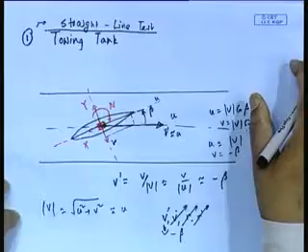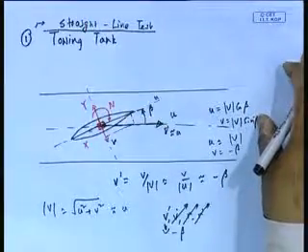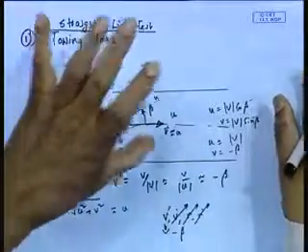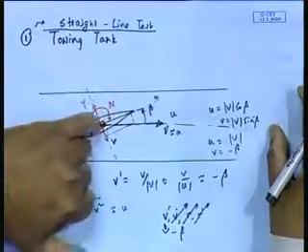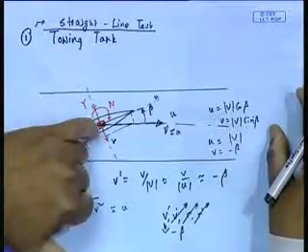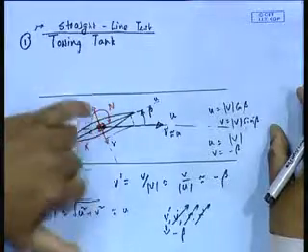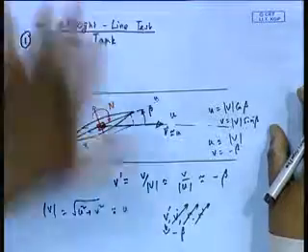See, when you do a measurement, the instrument will record, say, 20 Newton. But in this subject the coordinate system is very important, so you have to make sure which side the force is. If the force is on this side, I am calling it negative, because my axis system is positive. So, let us say the instrument showed me force on this side, 20 Newton. That means my measurement of Y is minus 20 Newton, right?